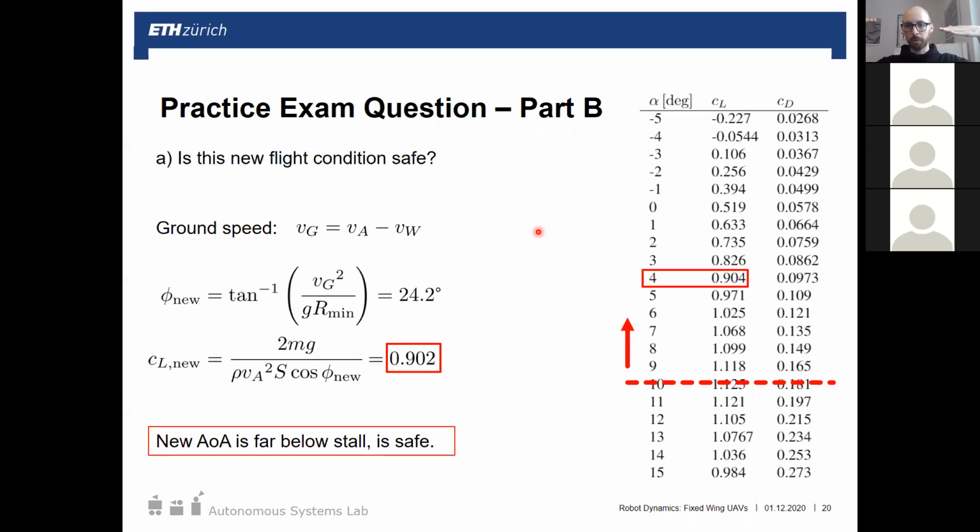So for headwind, since our box of air mass is shifting this way, if we wanted to maintain the same ground speed, we'd have to fly even faster than what we were before. So in this case, if the airspeed is the same, ground speed is less. Okay, I think that's also an easy way to think about it.